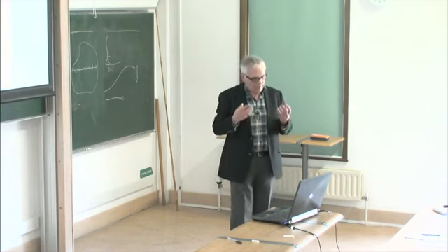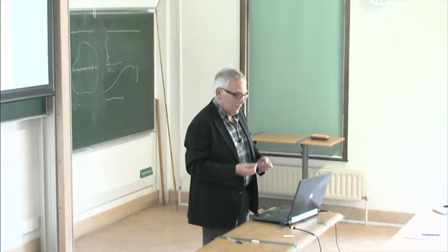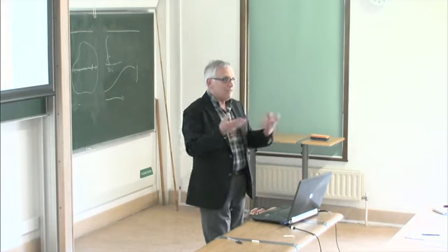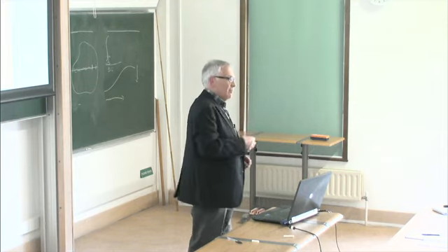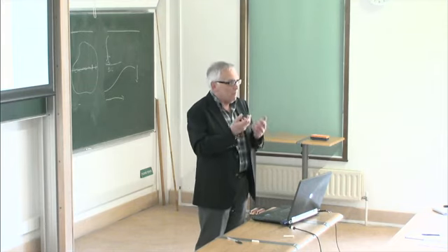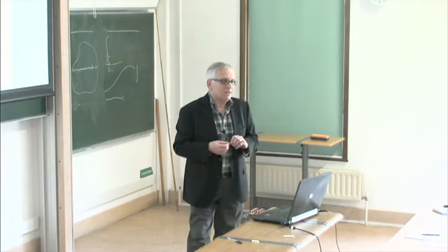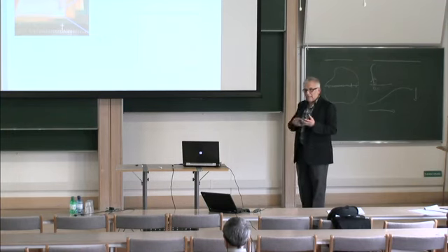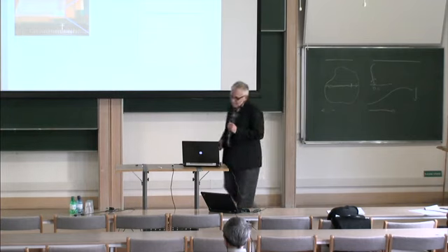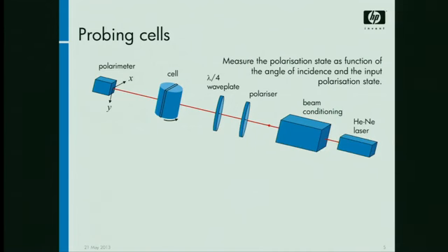And so part of it then is doing some experimental measurements, trying to interpret those results. The liquid crystals are too small, we can't see what's going on under a microscope. Typically for the bistable cells, as I'll talk about in a moment, length scales are typically about a micron period and 4 or 5 microns thick. So we can't just look down the microscope and say, oh yes, that's what's happening, or get much of an idea. So we want to be able to probe the cell, and this is one way of doing it.